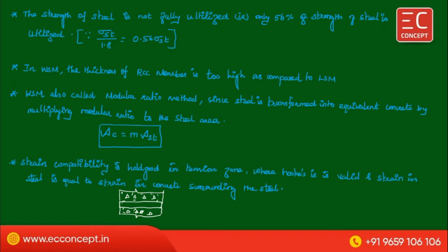Strain compatibility means when this bar is subjected to a tensile force, the bar undergoes elongation, and the same elongation will occur in the surrounding concrete.